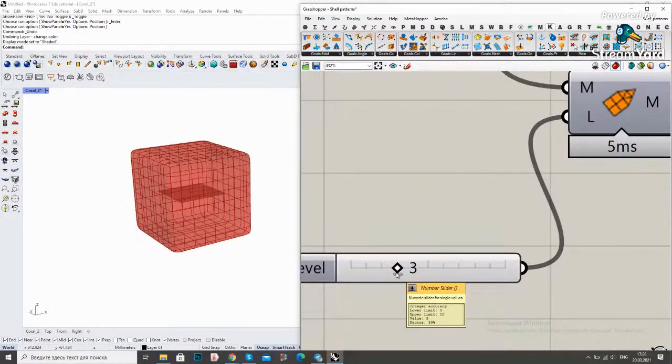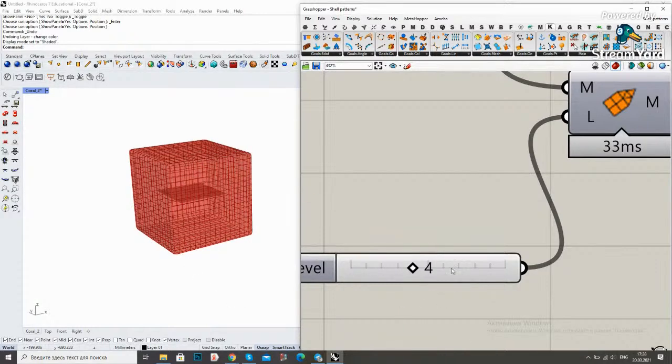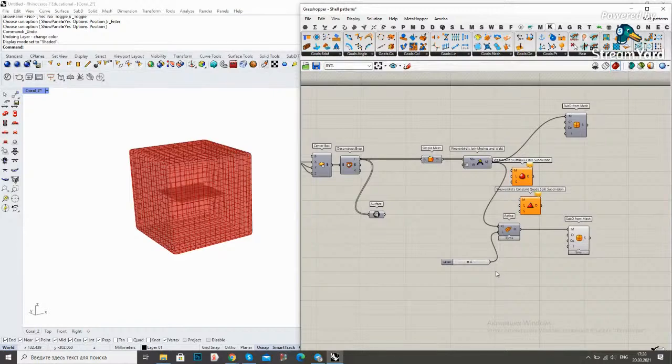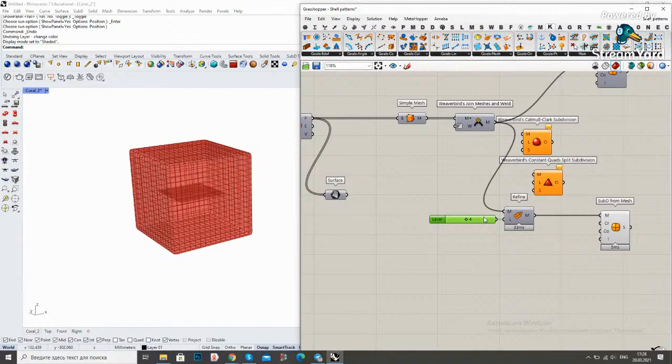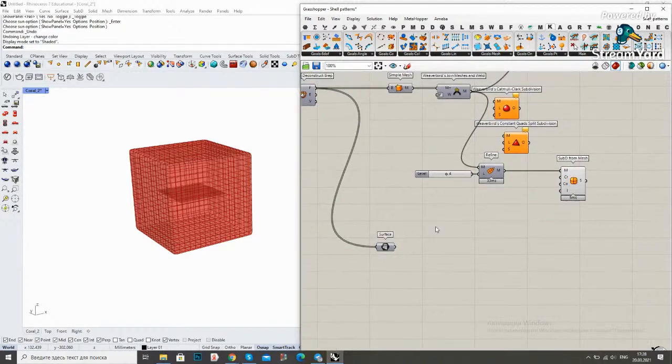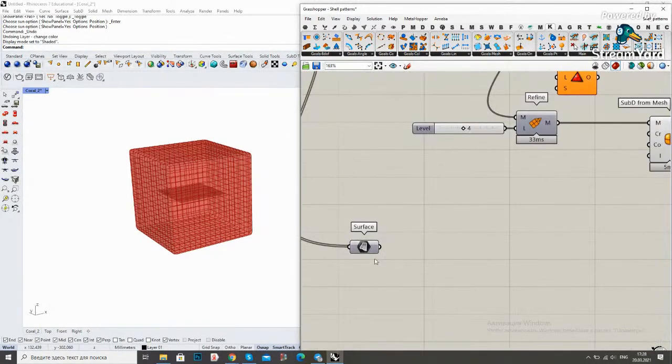So we already see that we can achieve this kind of control and this more rigid geometry by simply increasing the subdivision. But what we can also see is that this geometry becomes very, very heavy. You see that it already has 1,536 mesh faces, which is a lot for such a simple geometry, right? So we came up with another solution, which is much simpler, but allows us to achieve a very similar, in a certain way even more controlled, result.